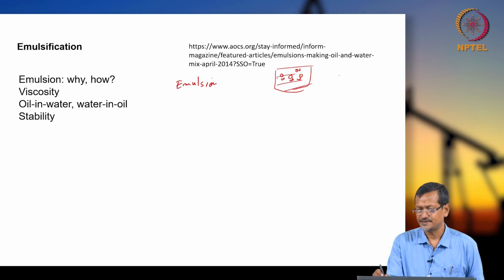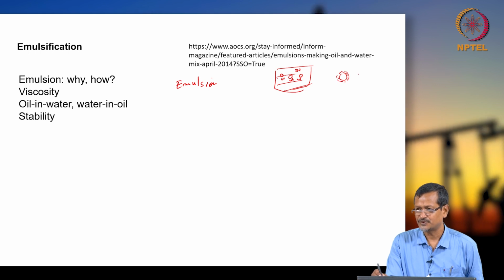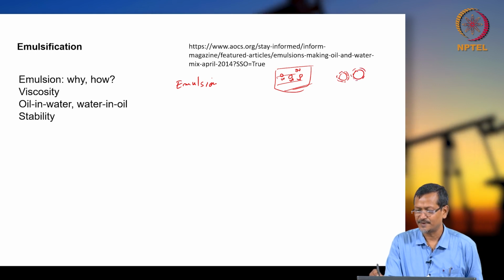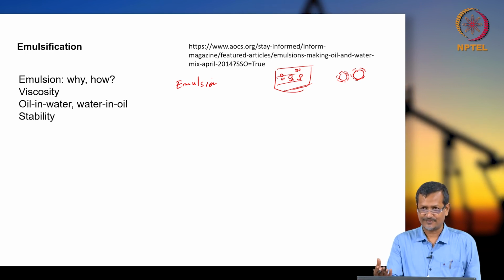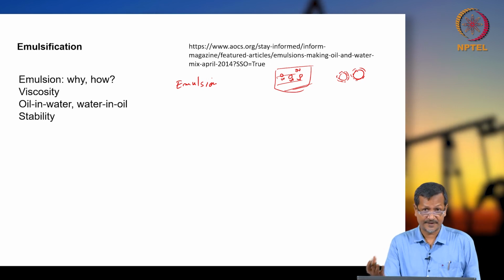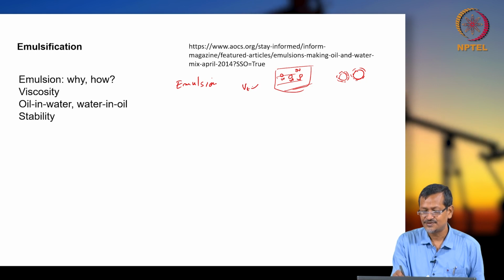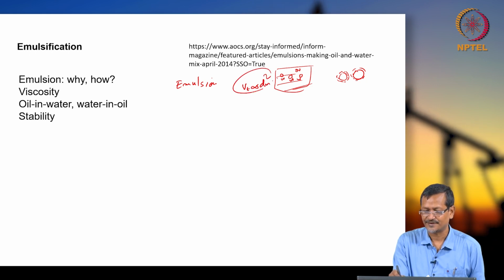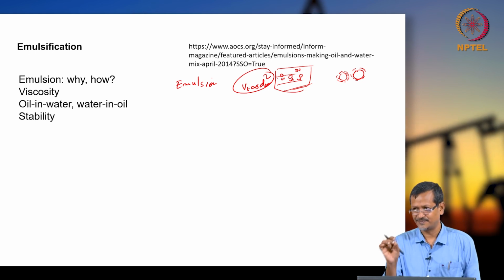Because the water particle will have a certain coating around it, two water particles will not mix with each other; they will have one barrier. So we have to understand why the barrier is getting created and how to break it, so that you can get a bigger particle, so that Vt, proportional to dm squared, can increase. Your purpose is to increase dm.